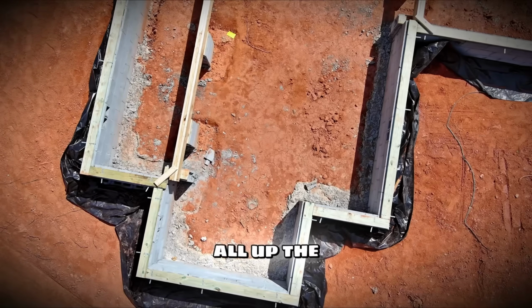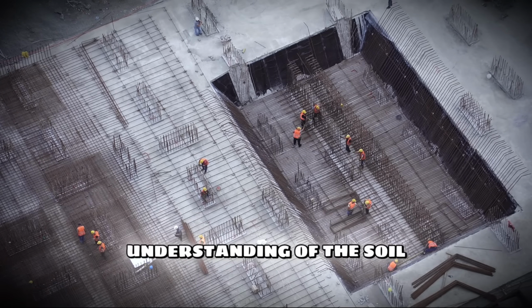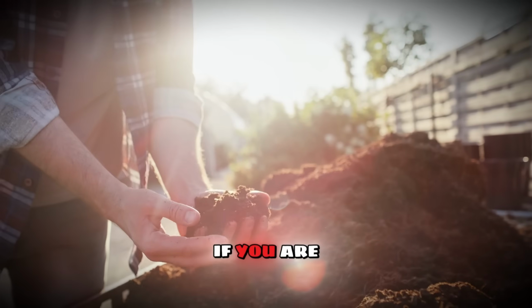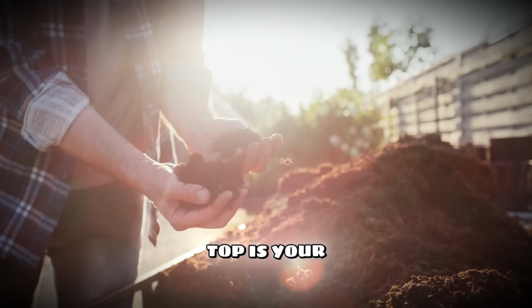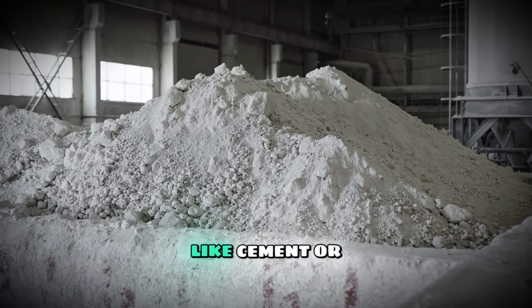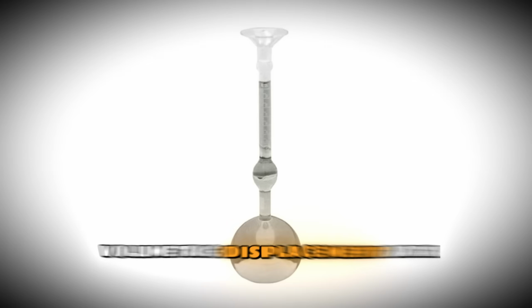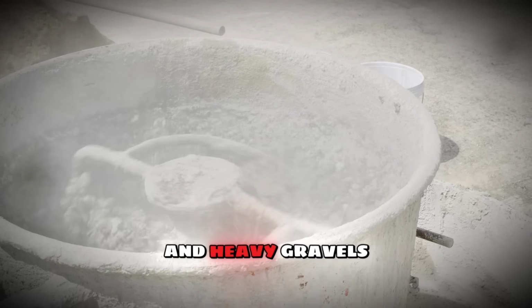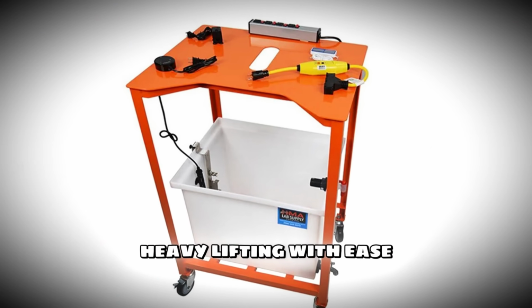To sum it all up, the foundation of your construction project is only as strong as your understanding of the soil beneath it. Knowing your specific gravity is non-negotiable. If you are dealing with standard fine soils and sands, the pycnometer jar and brass top is your precise go-to solution. If you are dealing with reactive materials like cement or ultrafine powders, the Le Chatelier flask will give you flawless volumetric displacement data. And if you are tackling coarse aggregates and heavy gravels, the specific gravity bench with a 30-gallon tank will handle the heavy lifting with ease.